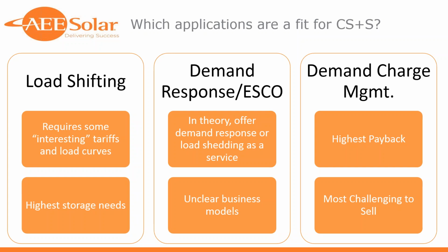You're taking large swaths of load, maybe not at a circuit by circuit level, but by sub panels, or really just offsetting as much of that metered, meter read power as possible. So you're doing this at a high level, and you're not doing this to shave peaks, but you're really trying to move big blocks of not power but energy from one period to another.